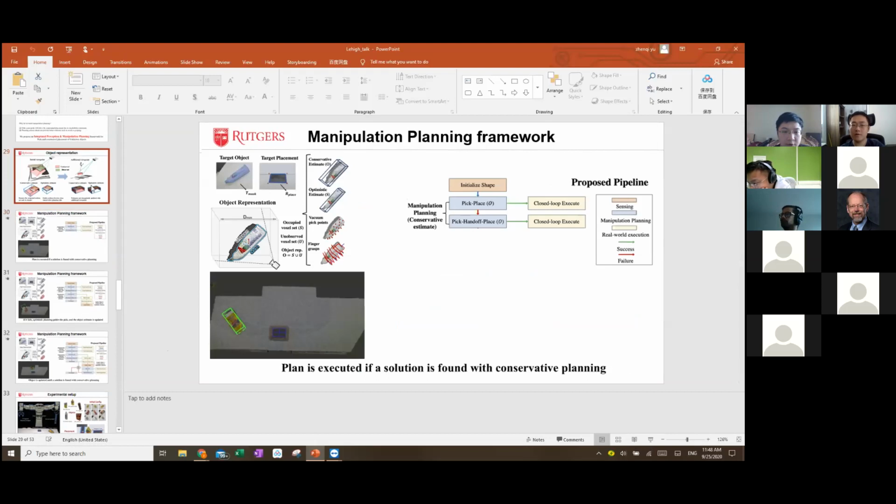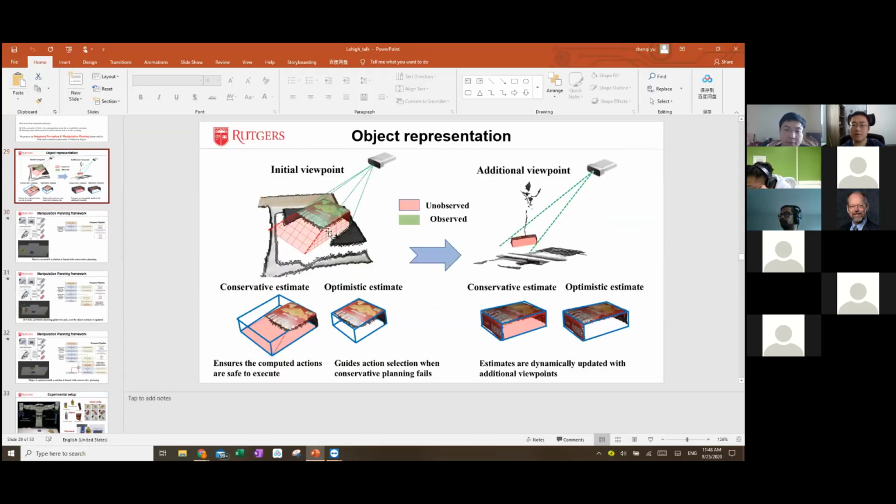Actually, it's not strictly a bounding box, it's voxels inside a box. Let's say there is a slope formed by this frustum, then the voxels under this slope will be represented as unobserved. For the voxel representation, there are 3 types. One is empty, which means any regions except the red or green in this case, where there's no voxel occupied in the object's frame.